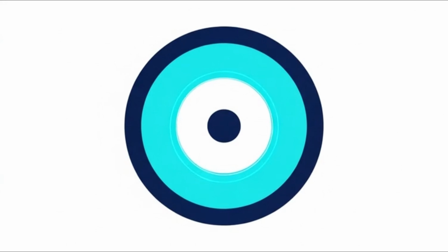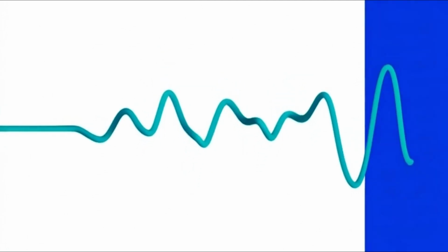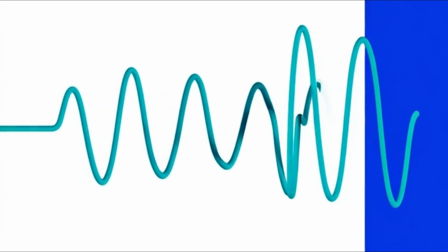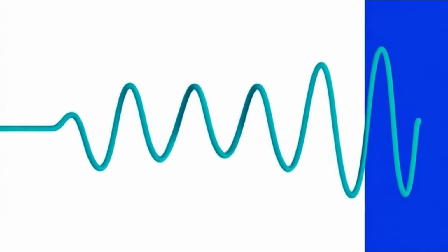You've probably seen the number 50 ohms everywhere in RF gear. Why? This is called characteristic impedance. It's not the DC resistance you measure with a multimeter. It's a ratio of the electric field to the magnetic field as the wave travels. If your transmitter is 50 ohms, your cable is 50 ohms, but your antenna is 75 ohms, that energy hits a wall. Some of it reflects back into your transmitter. This creates heat, potential damage, and lost range. Mastering RF is, in many ways, the art of making sure energy has nowhere to go but out the antenna.